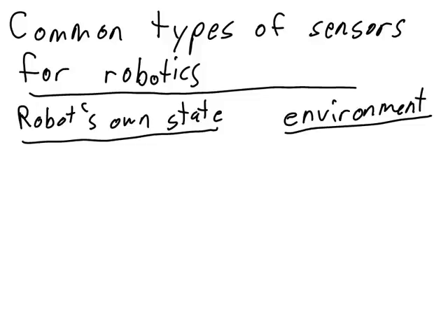For that, there are two types of sensors that are commonly used. The first is the potentiometer. A potentiometer can be used to detect either linear displacement or rotational displacement, and it's the type of sensor that we saw used in both of the types of actuators we've used in class so far, both in the linear slide potentiometer, and the potentiometer is also used in the servos that we use in class.